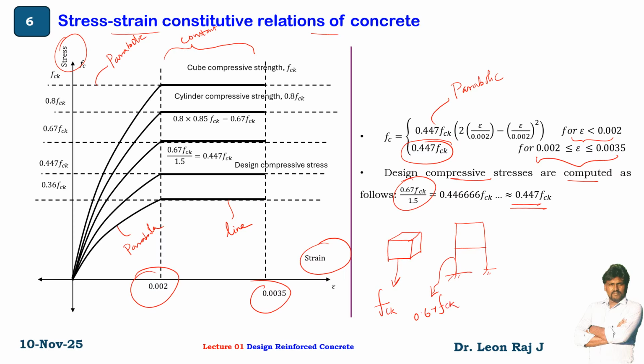For design stress, that is design compressive stress, design stress is equal to 0.447 FCK.